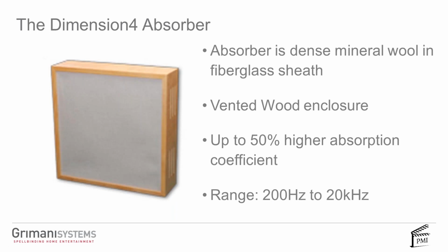What that does is give us a really good absorption coefficient down to about 200 hertz, and above about 2 to 3 kilohertz it doesn't turn off, but it tapers down a little bit so that the room has a little bit more high frequency reverb in it. Most rooms naturally have a loss of high frequency reflected energy above 2 to 3 kilohertz. Doing this is more expensive because you have to do the perforation and all that, but you end up with better performance.